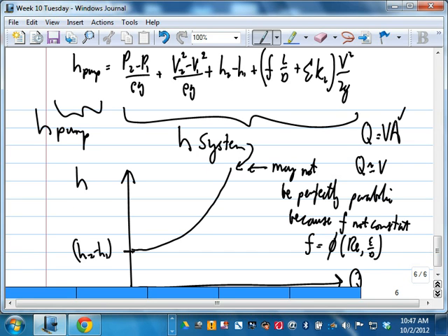If you have a particular problem, you can do that. If you've got time, maybe you cannot sleep, you can actually plot each data point here. What happens is Q here, here, and so on. So for each data point, you can find the flow rate, you can find the velocity. For each flow rate, you can find the velocity, calculate the Reynolds number, look up F, put it back inside here, and so on, and get back that number. Is that okay so far? Can be done. We'll do it in the tutorial.